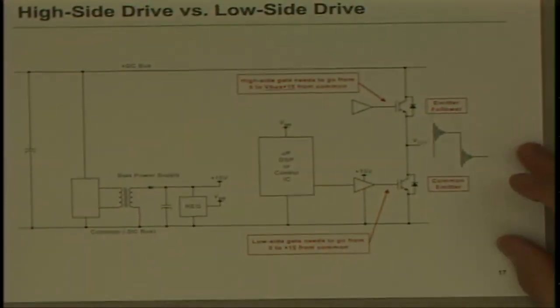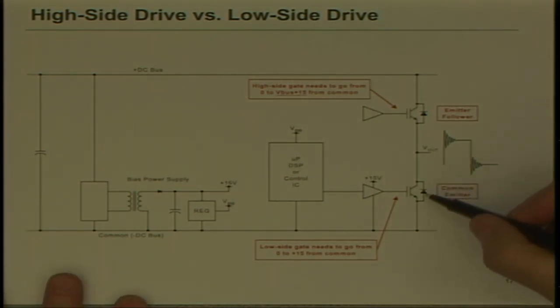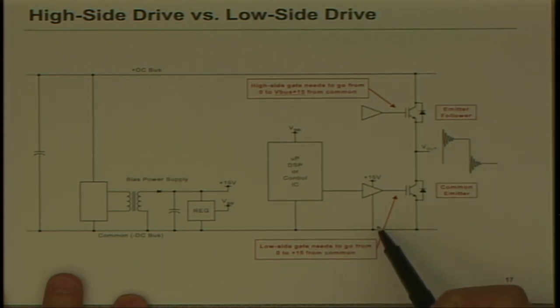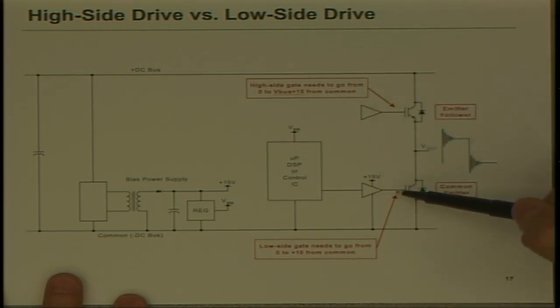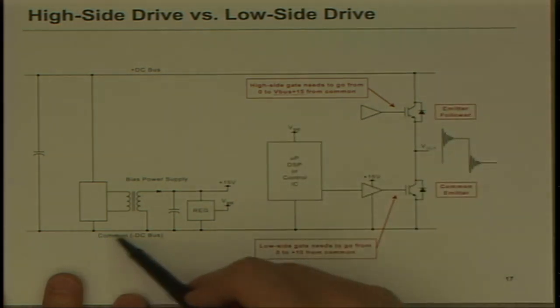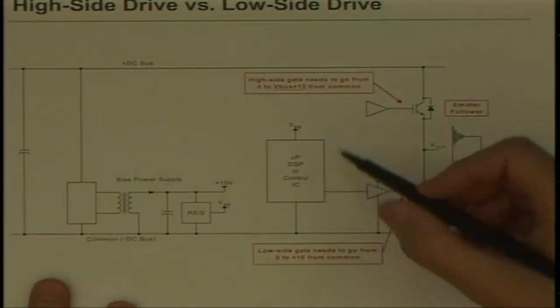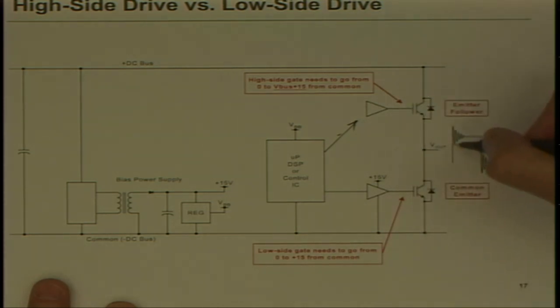Quickly talk about gate drive. The goal in gate drive, and again, we're talking most commonly about the half-bridge topology, which is used for UPS, motor drive, any kind of inverters. And there's different ways to do this. One of them is, and I'll show you in a minute, complete galvanic isolation. For lower power applications, commonly the gate drive circuit resides on the negative bus. So you can directly drive the low side. The high side is floating, and it needs some kind of communication here between the controller to be able to drive it. Because this whole thing, as my output flies up and down at 400 volts with ringing and overshoot,